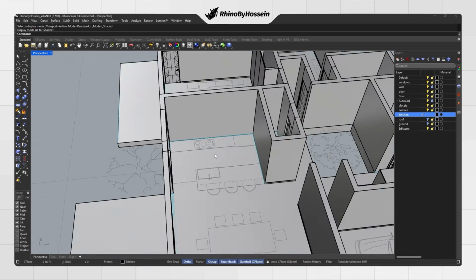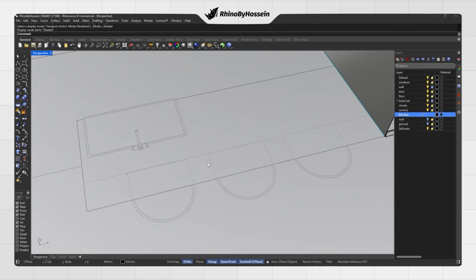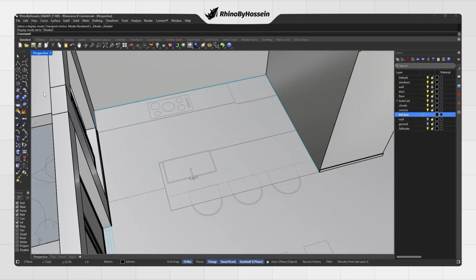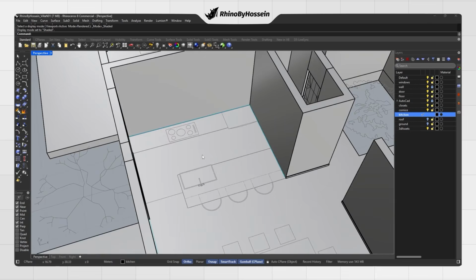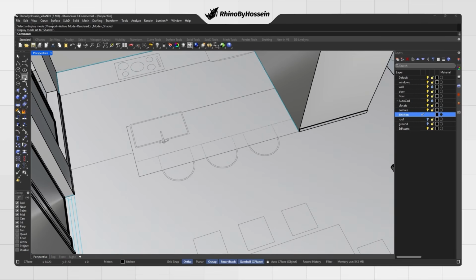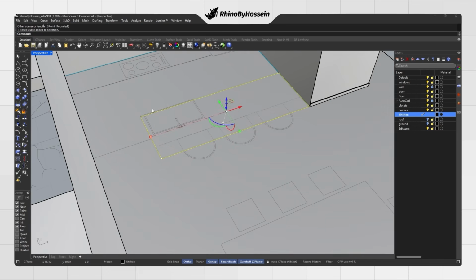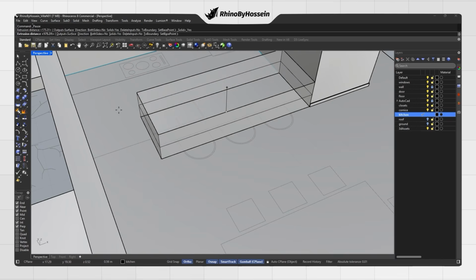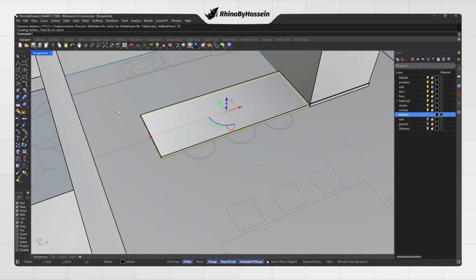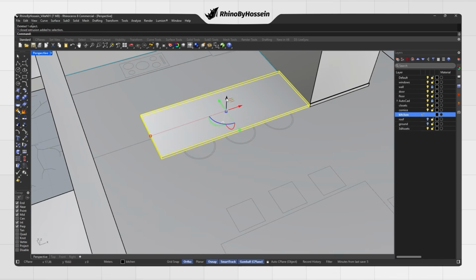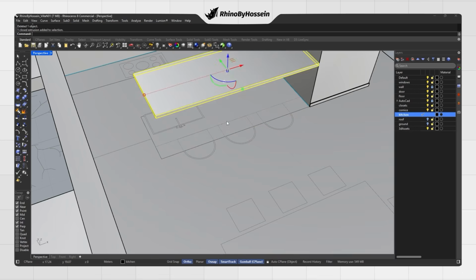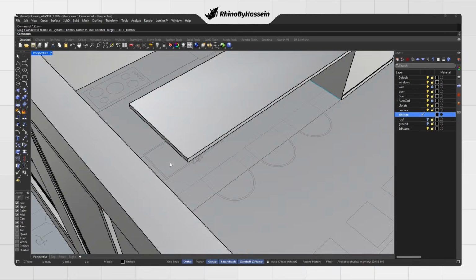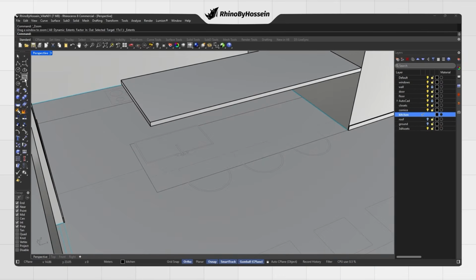All right, let's start building it. Since we've already repeated many of the modeling workflows in this video, I'll try to avoid unnecessary repetition and move a bit faster here. The kitchen modeling system is very similar to the wardrobes and the garage counter we built earlier. So, first, I start with the countertop. I model the countertop surface and then move it up to 90 centimeters so it sits at a standard working height. Now we move on to the lower cabinet space.